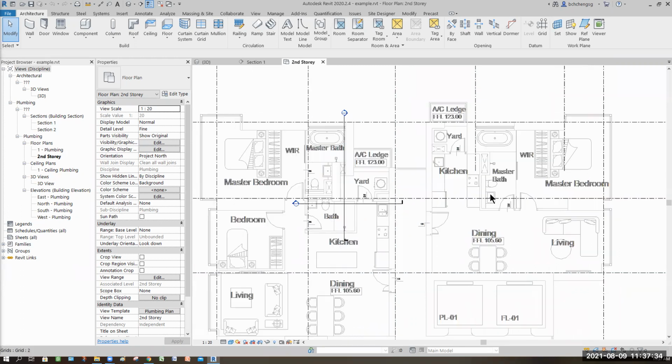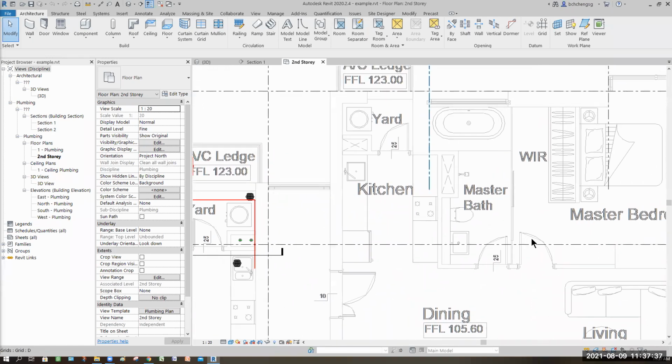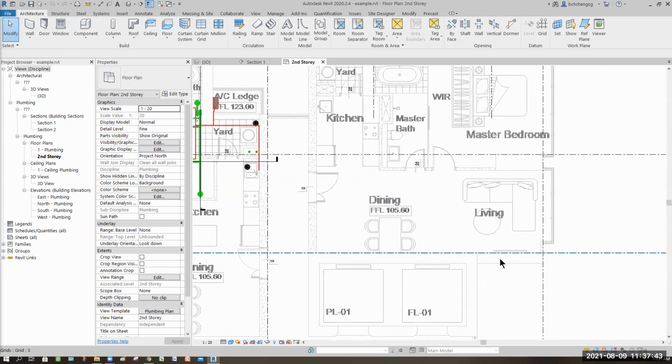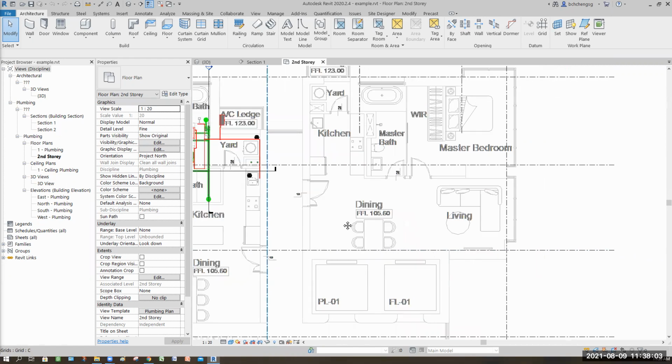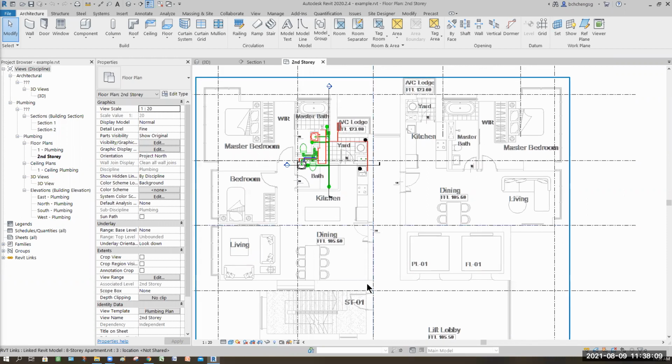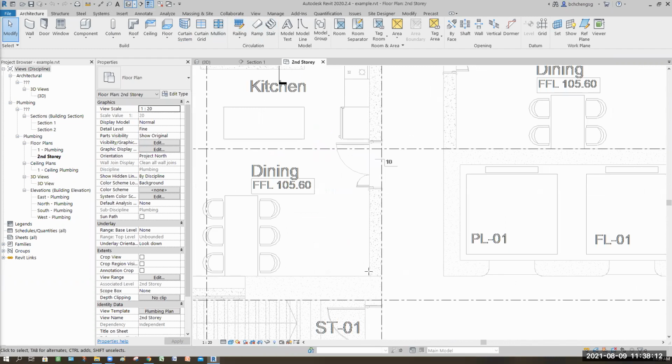Let me see, for this case there's only one column here, and 2 columns, 3 columns and 4. Now this is actually reinforced concrete, meaning your column can attach to this also. Okay, this is 400 thick. This is just a 300 thick wall, but I don't think it's load bearing. Maybe soundproofing, yes. Actually, you can tell by the thickness. You can measure it. Yeah, because this building I drew, I know.